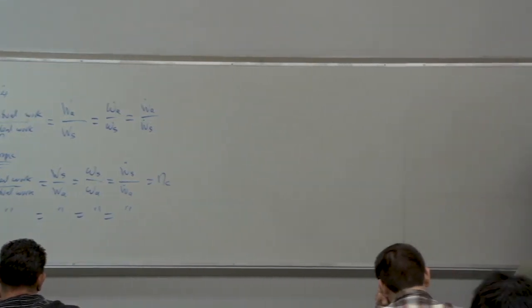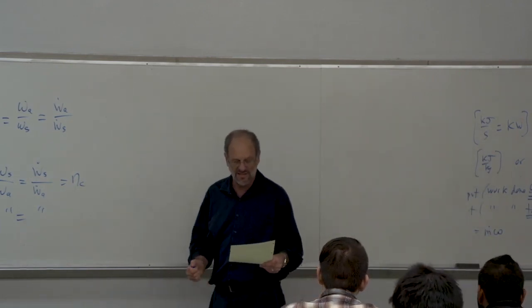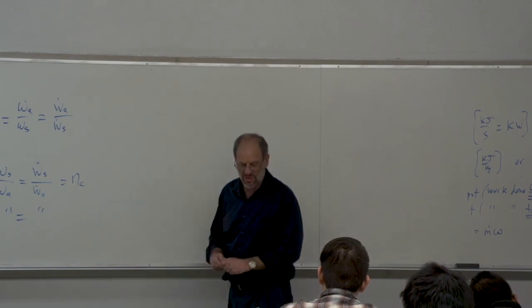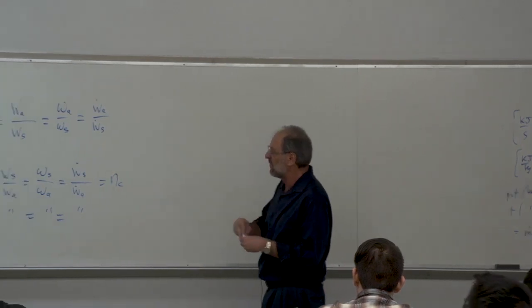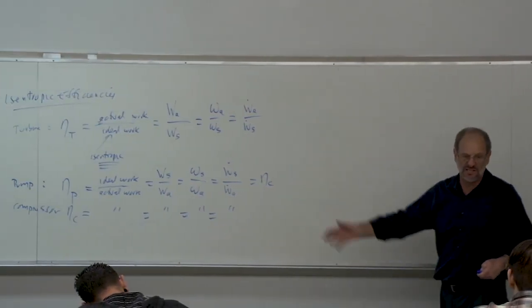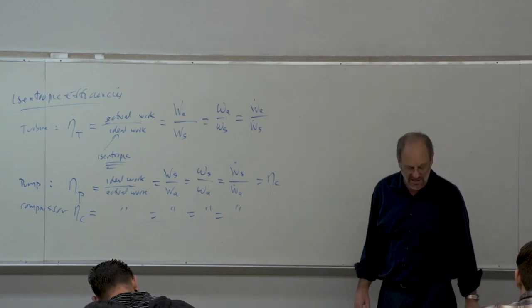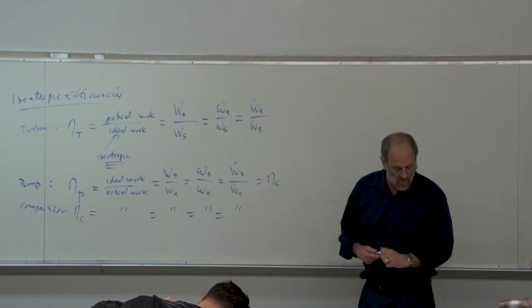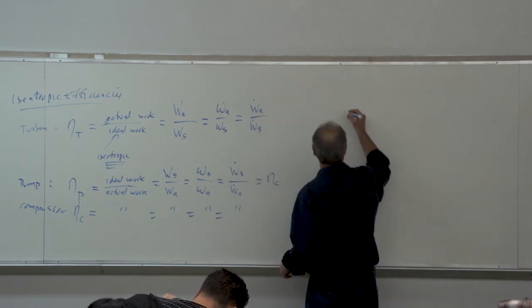All right, now again, this was all covered in your thermal class, so I'm not going to go into this in too much detail. But we do need a little bit more detail. Let's again note that for a typical steady flow device like a pump, turbine, or compressor, they're well insulated, we're neglecting any heat losses, and we're neglecting any kinetic or potential energy change. So what would this look like if we want to further manipulate these equations?